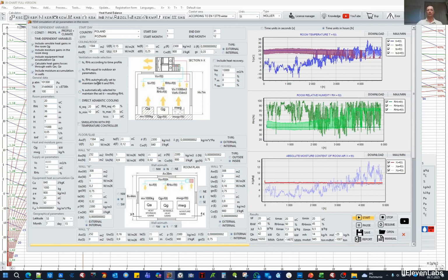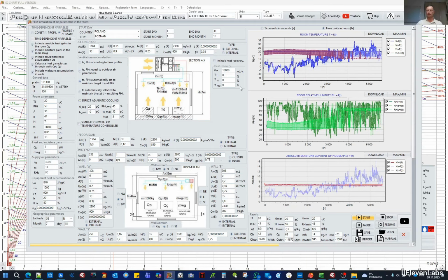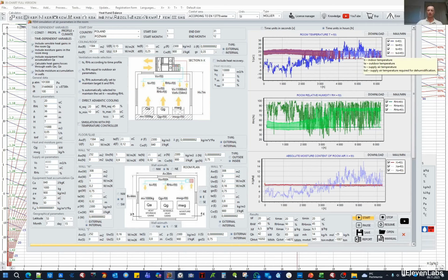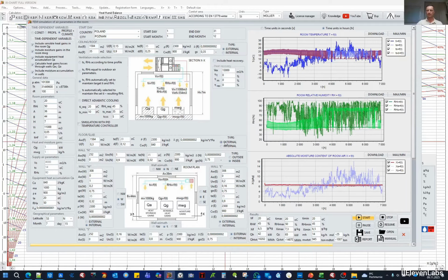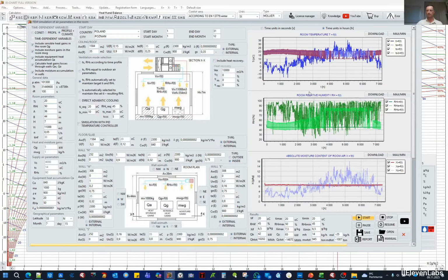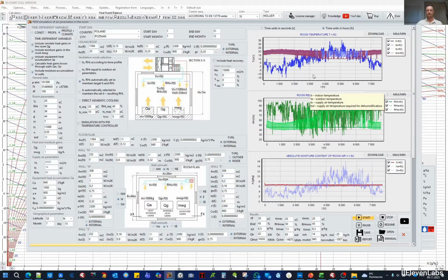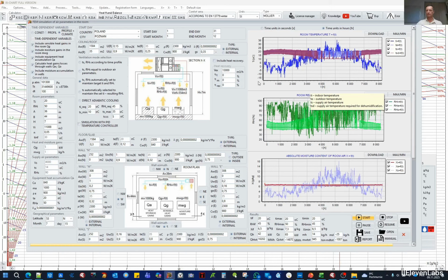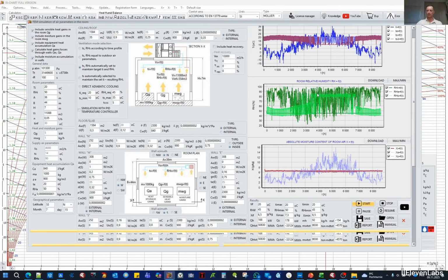We are performing, as you can see, calculations here with full climate control, and here will be an interesting thing regarding the distinction between these two supply air temperatures, the temperature for dehumidification and the supply air temperature for removing heat gains. Okay. The simulation has finished.